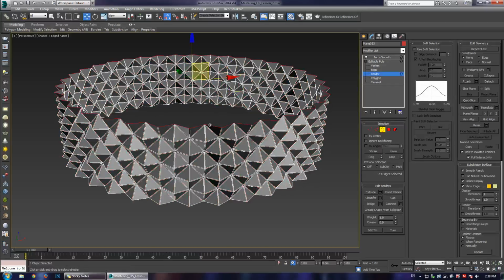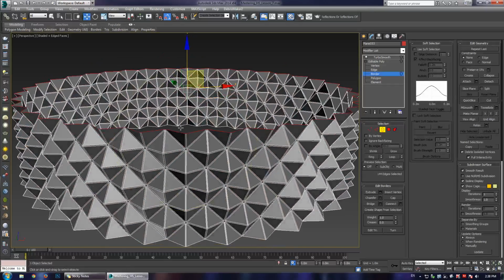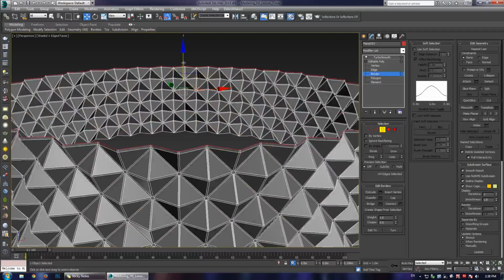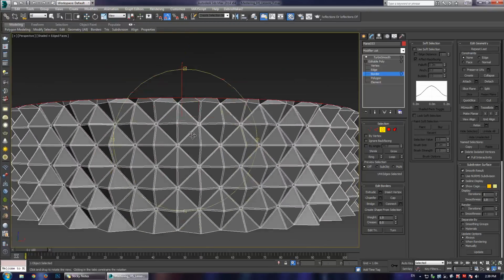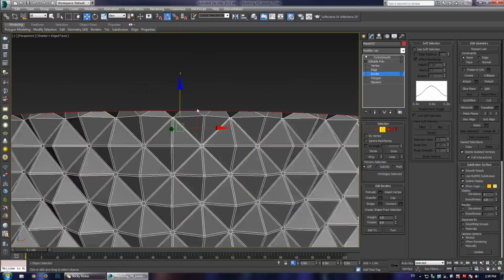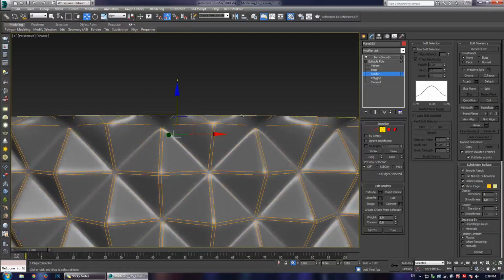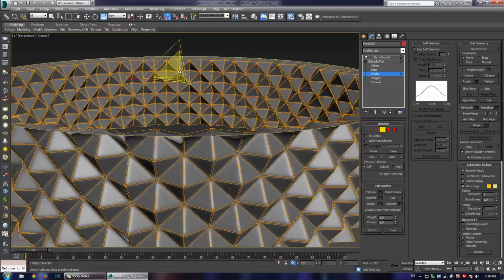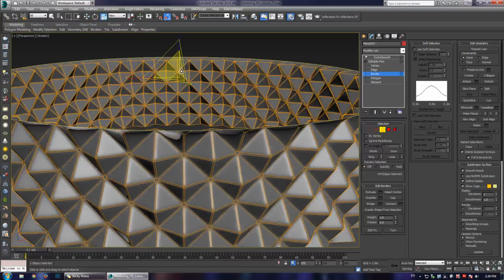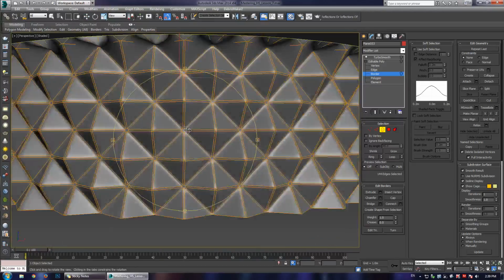So now the last thing to do really is to go into the top here and just extrude this out. And using our regularize tool, I'm just going to apply that. And it requires a little bit of trial and error about how big you scale this, because you'll notice now if I put Turbo Smooth on and scale in and out, it's totally up to you how you want this to terminate up the top.